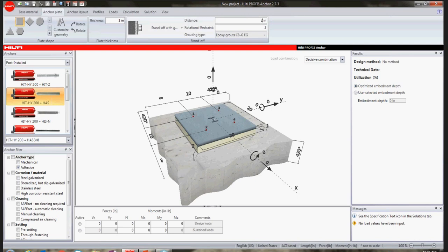Likewise, I'm going to zoom in again for shear. So for shear, we're doing the same thing. We're looking at the 3 failure modes respective to shear, and we're taking a look at those factored loads against those design strength capacities in shear at those failure modes. And again, we have concrete breakout failure as our controlling failure mode. So I'm going to bring us to the concrete edge failure mode here. Again, the same thing. We have all these calculations now with respect to shear.